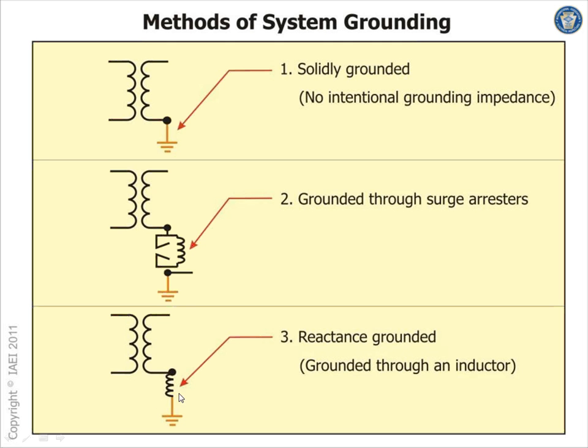You can also have another one that's the ungrounded system that we looked at, or something called reactance or impedance grounded system. So the grounded system will get you a voltage to ground, stabilize the voltage to the ground, and get rid of the transient. Ungrounded system gets you survivability of the system. So if you have the first hit, the first ground fault, you're still standing, the system is up and running. The second ground fault will get you down.